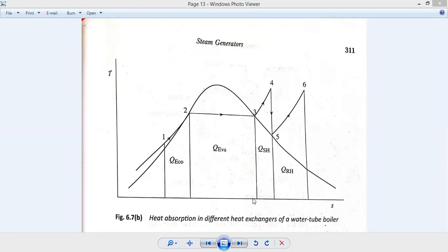So nowadays we are going for superheating and reheating, and that too with the help of the same flue gases, without spending anything more than this flue gas itself, and less boiler surface than older units. The fraction of total heat absorbed in superheaters alone may be as high as 60% in a modern boiler.